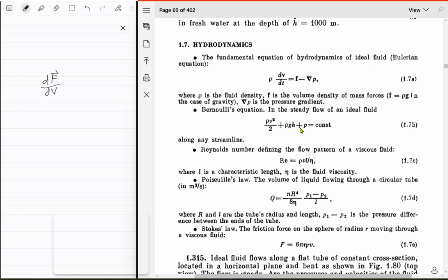Suppose at that particular position you take any block of water, or whatever fluid you have, and you measure the external forces, other than of course the pressure forces, acting on it. The force is equal to, let's say, d capital F vector, and then you divide that force by the volume.